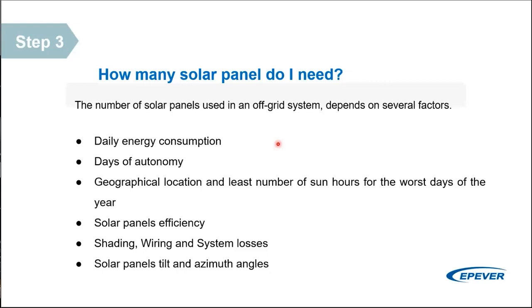Labels of solar panels contain useful information about the array. You will see numbers like VOC and ISC, and these are the two important characteristics we will be using in designing the standalone system. VOC, or open circuit voltage, occurs when the positive and negative leads from the solar array are not connected, and this results in the highest voltage the cell can produce. ISC, or short circuit current, occurs when the positive and negative leads are connected directly to each other, resulting in the highest current that the array can produce.